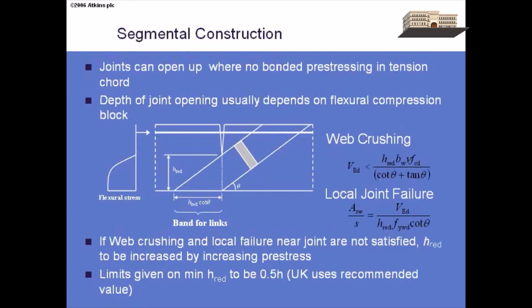I haven't specifically got a slide there, but if you then need shear reinforcement, the method of calculation is exactly the same as it is for reinforced concrete. So we only consider the design for the links. We have the variable angle truss model, and we need Z, the lever arm, in that formula, and Z has to be based on the flexural analysis for the pre-stressing.